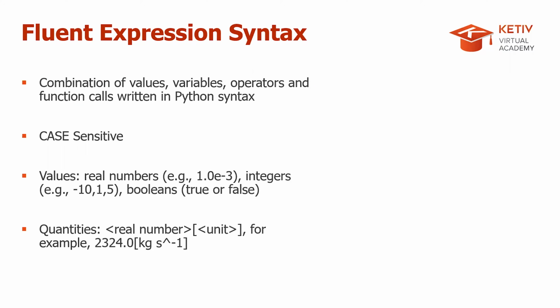these expressions quite easily. If you do it 1 or 2 times, you'll know how to use the right operators, right brackets, how to assign the units, variables, etc. Fluent expressions are case sensitive, so keep that in mind. All types of values can be included, real numbers and integers, even Booleans like true or false.